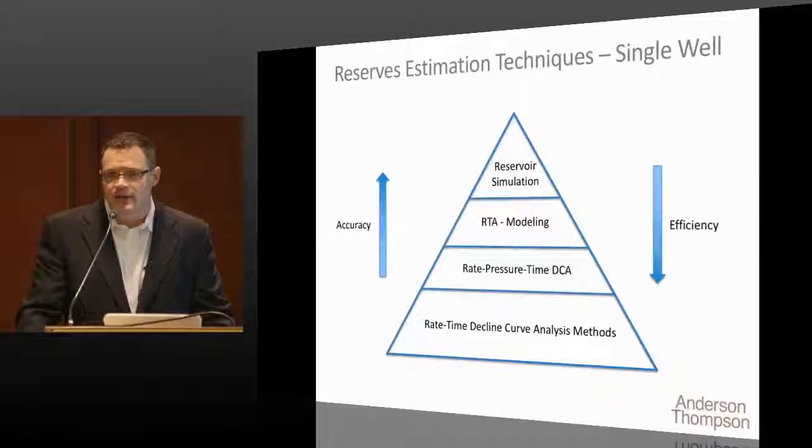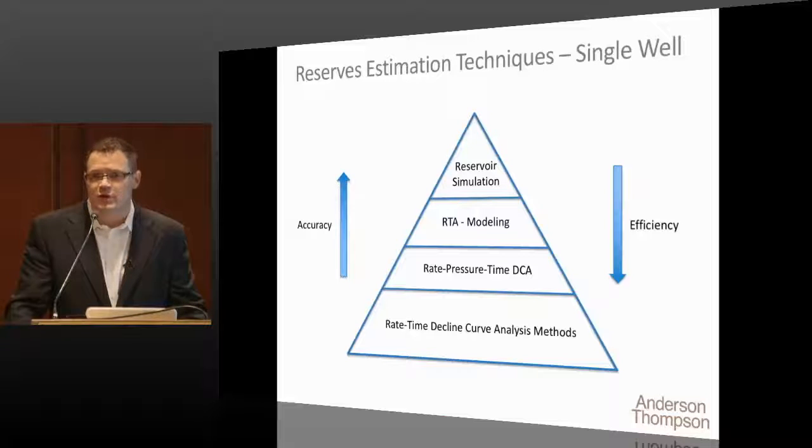These things are terrific because they can be applied to a large well count and they can be done fairly efficiently. Moving up the ladder from that, it doesn't take that much more effort to incorporate the flowing pressure response. Using just basic wellhead data, or wellbore schematics if we had them, we can convert these surface wellhead pressures to sand face without too much trouble. This would be particularly advantageous for companies that are looking to do just a little bit better than rate decline, especially when you're dealing with highly overpressured, rate-restricted programs where you can't decline a well that's on constant rate very easily without applying a rule of thumb. So that pressure information is great. We're seeing more companies do this.